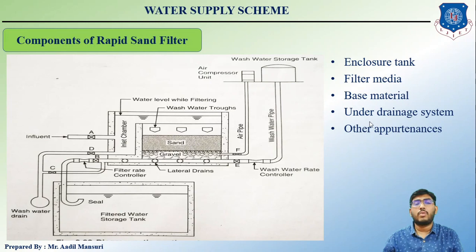So if I talk about the water flow direction, then the water will first enter the sand layers, then gravel layers, then it will enter into the perforations, right? Then into the laterals, then into the manifold, and then the outlet.